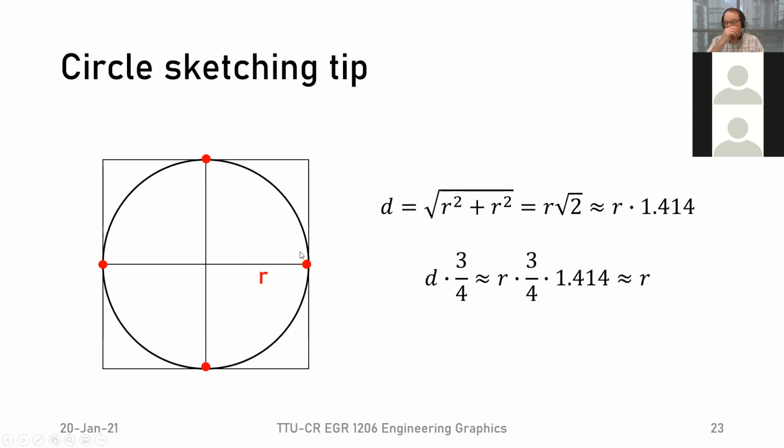But that still often gives us pretty odd looking shapes when we draw these, especially if they are a little bigger. So it's helpful to add another set of points. And to do that, we draw the diagonals into our box like this. Now if you look at the diagonal, there's my pen, right? I see that I get these triangles everywhere. Right? I get this triangle. And of course, I know if the radius is here, then I also have the radius there.